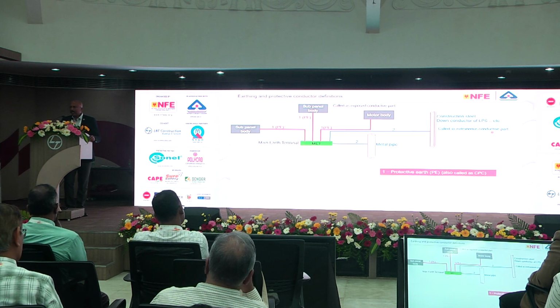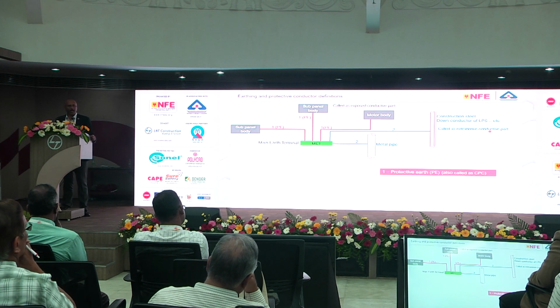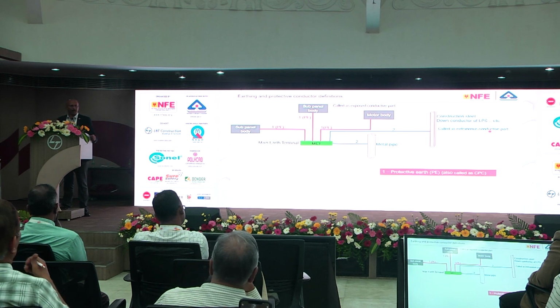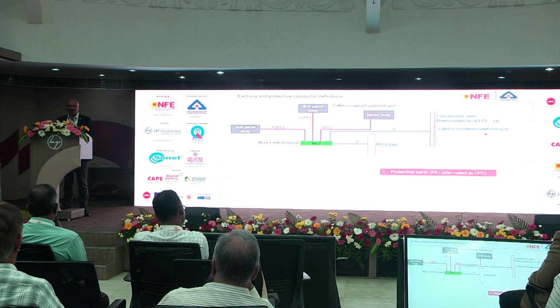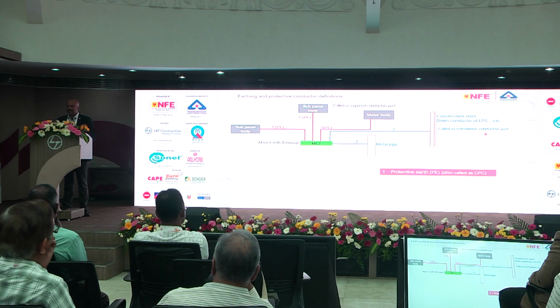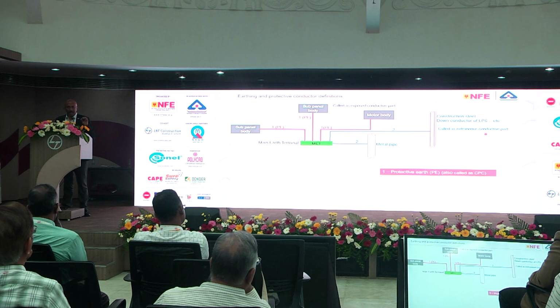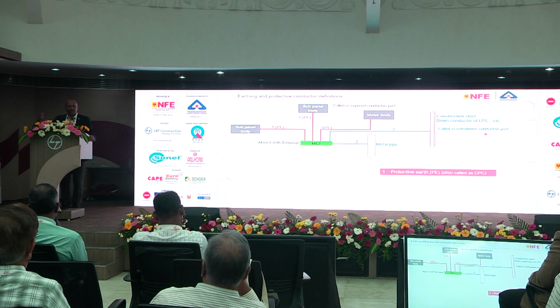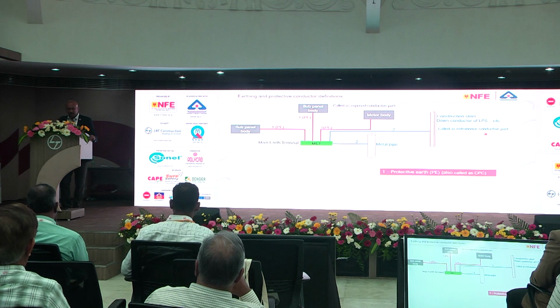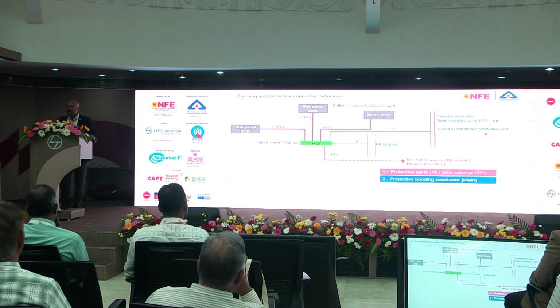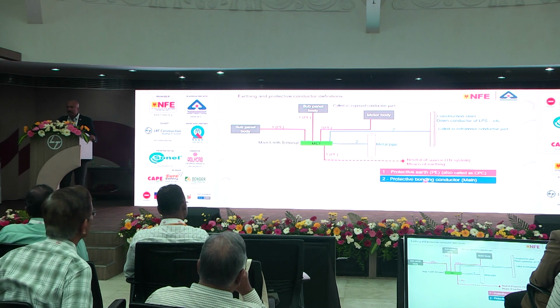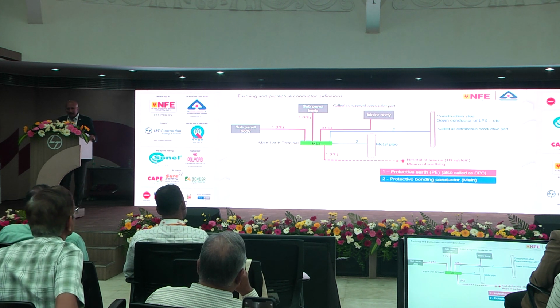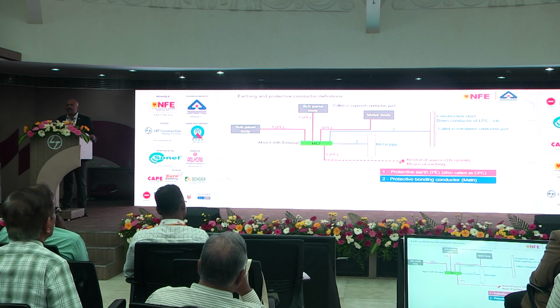Now you have extraneous conductive parts such as the metal frame of your building, metal pipe of your building, maybe sewage pipe, I don't know how many types of things, air conditioner duct and all. So these must be connected to the MET independently. Independently means under any condition this connection shall not go; you should not disconnect it. In future, somebody making a maintenance shall not disconnect it under any condition. This is called protective bonding, and the wire used for protective bonding is called the protective bonding conductor.